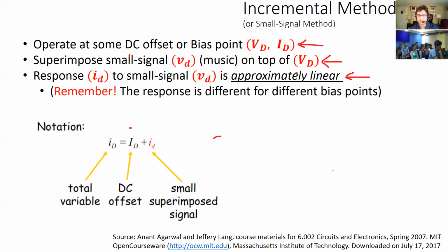Okay, so quick introduction on small signal modeling, which sometimes will be called the incremental method. If you remember, this is for nonlinear circuits. So if you have a nonlinear device or a circuit, you want to linearize it at a certain point because your voltage or your bias point doesn't change much, so it makes your analysis much simpler and gives you a deeper intuition into the circuit by doing that.